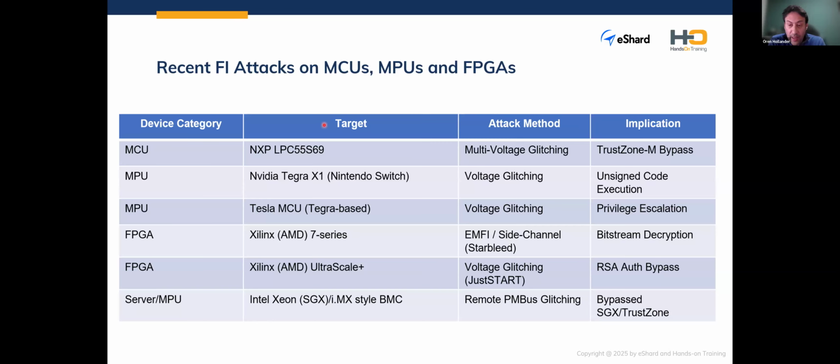Okay, so you can imagine that what's actually happened is that on this device, a precise glitch during the image verification stage, the authentication stage, doesn't corrupt the image itself. It corrupts the program counter. And by that, this wild jump sends the CPU to a memory address of the attacker's choosing, where he can run his payload.